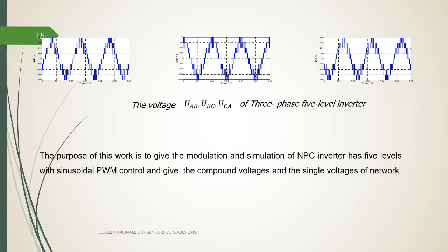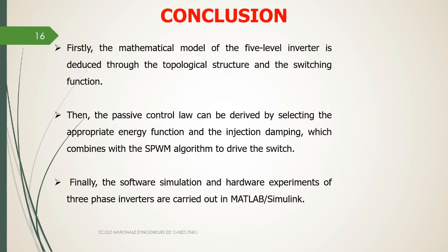Then the passive control law can be derived by selecting the appropriate energy function and damping injection, which combines with the SPWM algorithm to derive the switch. And finally, the software simulation and hardware experiments of the three-phase inverters are carried out in MATLAB Simulink.